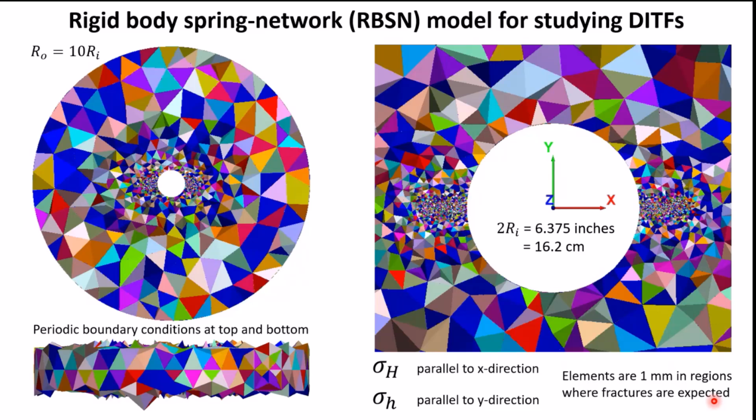Okay. Yeah, I know exactly what you mean. Fracture toughness will depend on the size of the rigid blocks, definitely. And in order to get close enough that you get the right ratio of tensile strength to fracture toughness, there's more or less a linear relationship between the two. You have to get basically to the grain scale in terms of size. So I got pretty realistic values for the tensile strength and the fracture toughness. But I can't use that size in the entire model.